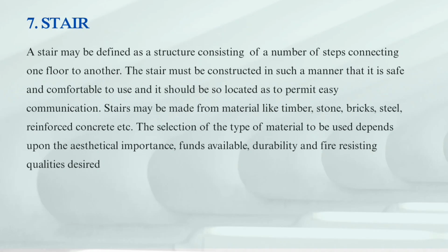Now the next component part is the stair. A stair may be defined as a structure consisting of a number of steps connecting one floor to another. The stair must be constructed in such a manner that it is safe and comfortable to use, and it should be so located as to permit easy communication. Stairs may be made from material like timber, stone, bricks, steel, reinforced concrete, etc. The selection of the type of material to be used depends upon the aesthetical importance, funds available, durability, and the fire resisting qualities desired.